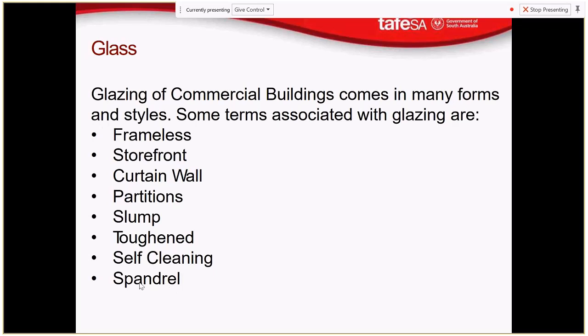And spandrel, spandrel is a term to describe any floating building element that goes between two supports. So in this scenario, we're probably talking about a large glazed unit that would go between two points of support elevated up, like a portion of curtain glazing wall.